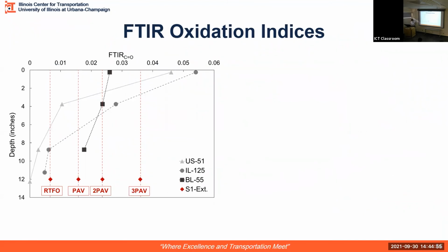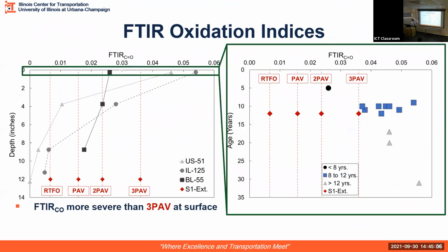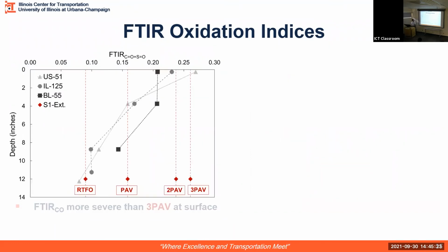If you look at the distribution along the depth of the pavement, at the surface you see more of higher index values. Makes more sense. And if you look at the distribution, there is some rough distribution because these are more populated points. If we have more populated points at 17 years or 20 years of age, we might see a distribution. That distribution within an aging level makes sense because of differences in chemistry.